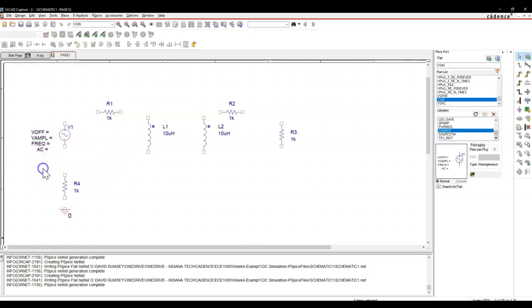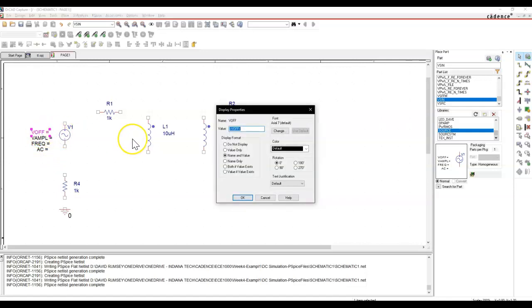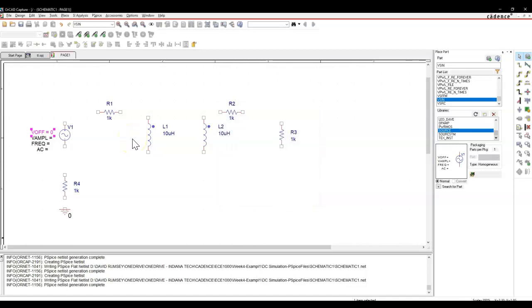So I'm going to add that there. And now I have a lot of parameters I have to set here as well. So before I even connect everything up, let's go ahead and do this. Now, this V offset, it didn't say anything about that. Unless otherwise specified, that V offset's always 0. The offset is basically referring to a voltage offset.